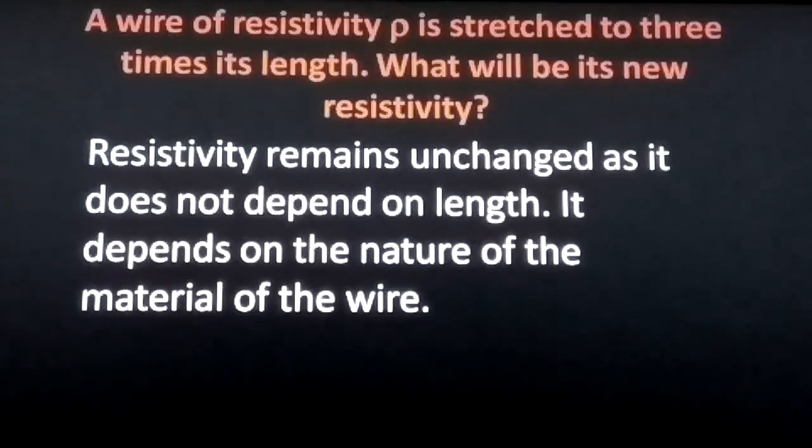Now students, we will see this. If a wire of resistivity rho is stretched to 3 times its length, what will be its new resistivity? That means, if the length of the wire is increased to 3 times, what happens? Observe. The resistivity remains unchanged as it does not depend upon its length.